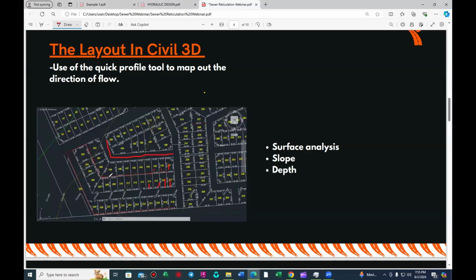So as you can see, in your low income housing, your residential stands are designed in blocks, which means they're designed back to each other. I'm sure if you've ever stayed in a high density suburb, you understand what I'm talking about, or even in a median income density. There is a part where you share a perimeter wall with your opposing neighbor. So how we lay our sewers is we lay our sewers in between those stands, right? Because it's cheaper that way.